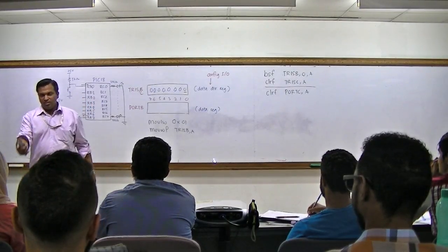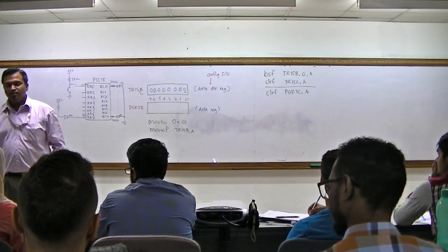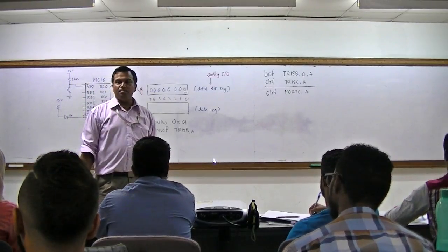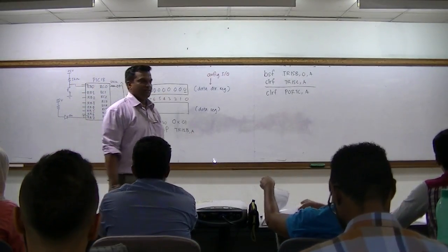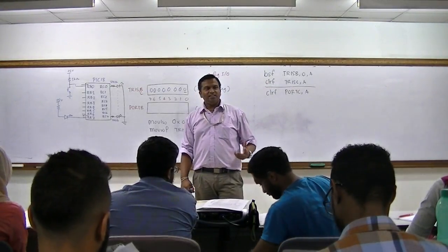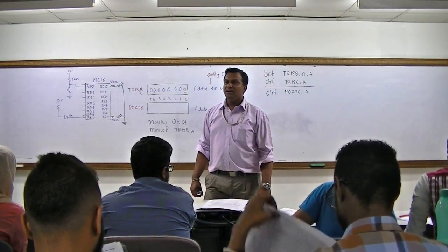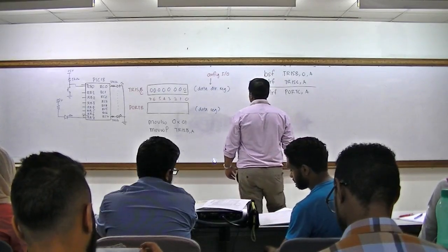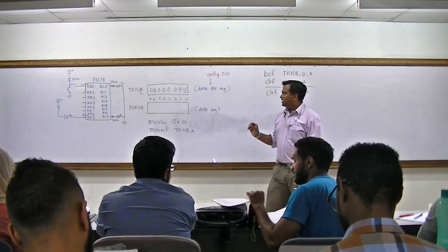If you see in your instruction set under the bit-oriented instructions, first page, there is one instruction known as bit test file register. Bit test is actually testing the bit. There are two bit test instructions. One is bit test file register skip if set. One is skip if clear. So in either way, you need to use the bit test because it checks the port.